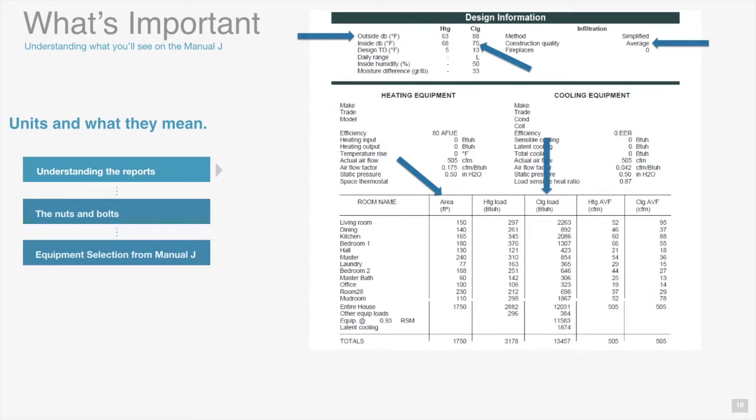The cooling load, this is the important part. The sum of these numbers is how you pick your unit. This is largely talking about the sensible load on the equipment. Down at the bottom, you'll see the latent load. That's 1,874 BTUs per hour of latent load on this particular house. But that's not the most important number. The most important number is just the sensible number, which is going to be right here. You see that entire house number right there, and you can cover the equipment loads with it as well. But that's the number that you're going to look to size the equipment.